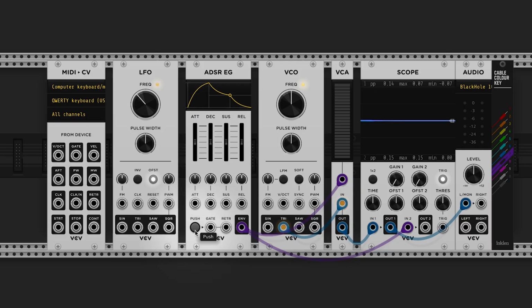When the button is released or the gate signal is lowered is when we will move from the sustain stage to the release stage and lower our level again from whatever the sustain is set at back to 0. When paired with a voltage controlled amplifier, we can control the overall envelope of whatever our sound is, allowing us to play a note.